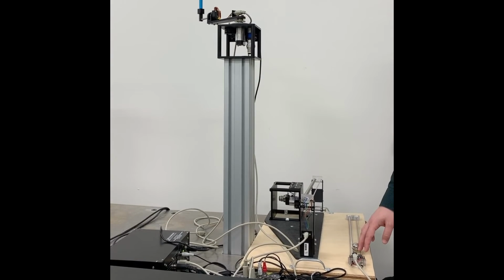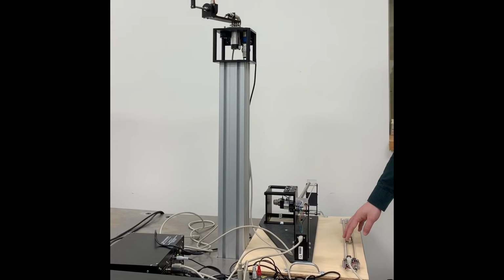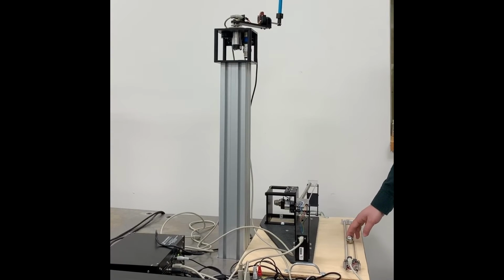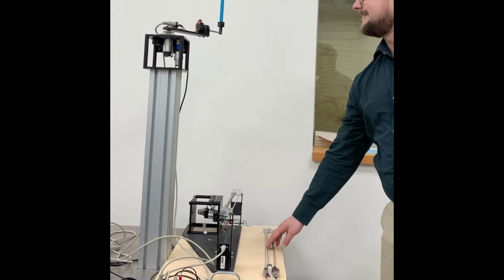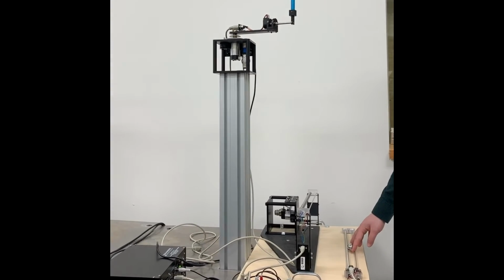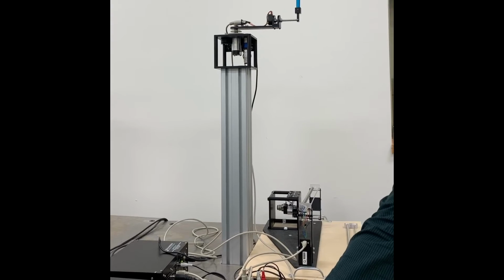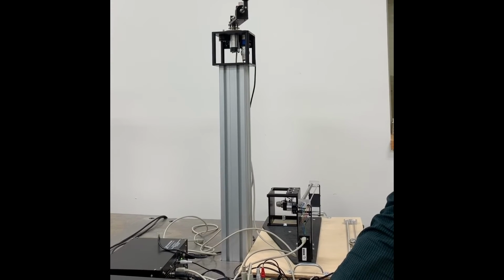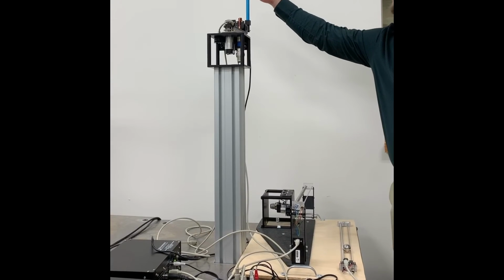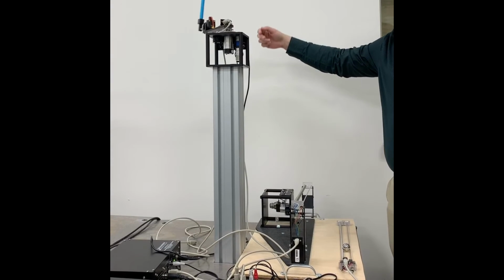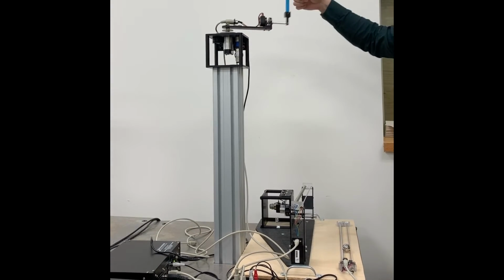The balance stage is activated as the linkage reaches the top position within a threshold of plus or minus 15 degrees. The balance stage calculates the voltage required to catch and maintain the vertical position of the linkage. It also requires a reset of the Q2 position so that it equals 0 when at the top of the cycle. To find gains that would balance the robot, we used the equations of motion modeling dynamics of the robot that we previously derived using the Hamiltonian.